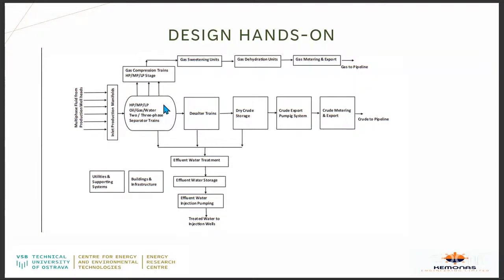It's more expensive to replace a vessel like this, like a three-phase separator. So if you want to design this, you have to use a very suitable material that will handle the corrosion and corrosivity from the feed that you'll be handling. But for piping systems, you can easily replace a pipe spool today and continue operation the same day. But for process equipment, it takes a longer time. So the time can be translated to cost, and also the cost of the equipment.